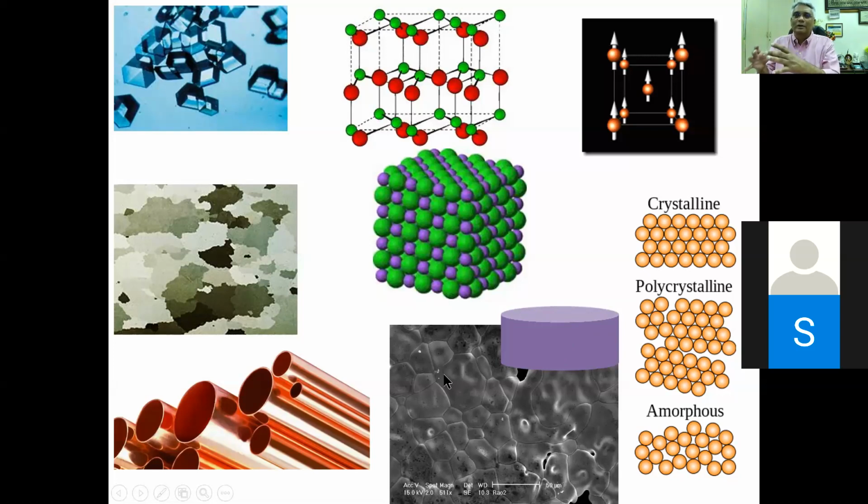If I leave this polycrystalline bulk outside for some time, after a few weeks, you may see depleted oxygen levels leading to changes in physical properties. So you do the electrical resistivity measurement today, leave it outside, and then test it after a few weeks. If you start seeing a change in physical property, that means the material has been subjected to atmospheric degradation. This is one of the ways in which device quality materials are tested, whether they're prone to atmospheric degradation or not.